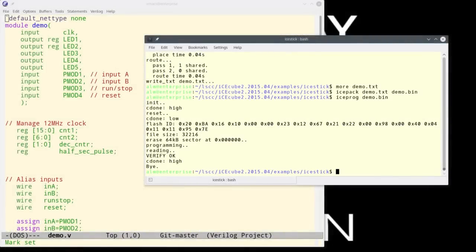And so that about wraps this up. We took a Verilog design. It had some combinatorial logic. It had some sequential logic. We synthesized it. We did a place and route step on it. We created a bitstream, and we loaded it down into the board. We also simulated the Verilog, so we were pretty sure it would work when it went onto the chip, and it did. So, granted, this is about the simplest FPGA project you could imagine.